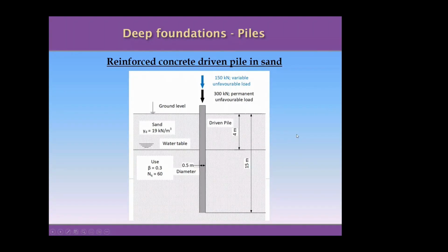So in the first place, we need to understand, when we are talking about piles, what type of structure a pile is. A pile is a structure that is very similar to a column that is inserted in the soil with different methods. You can have a driven pile or you can have a bored pile, where you make first the hole that will contain the pile and afterwards you pour the concrete in there, for example, or you install the steel pile in there. And the driven pile is driven in the soil using a hammer, a hydraulic hammer, as you saw in the videos during the last week or the week before. I don't remember exactly.